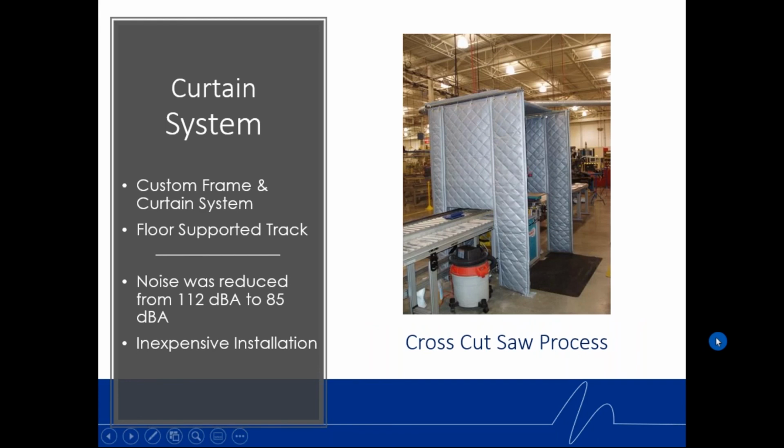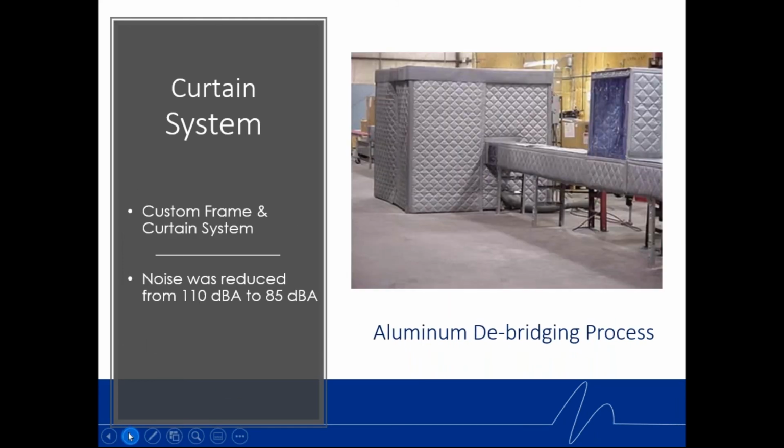Systems don't have to be very difficult either. This is a simple floor supported track system. They were at 112 dBA. It was a cross-cut saw cutting aluminum extrusions, and you know how loud that is, and mostly mid to high frequency noise. So this was able to take it from 112 down to 85 dBA in the background of this photo. The only person that needed to wear hearing protection was the operator.